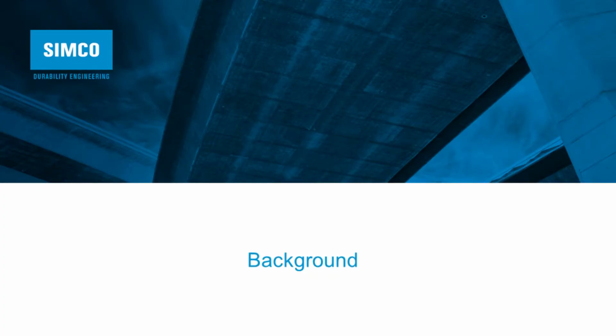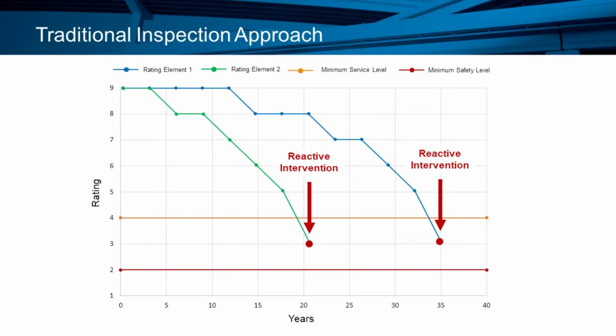Traditionally, inspections are done by rating bridges. This is an example. Ratings can be different across agencies, but the idea is to inspect on a regular basis and then assess a rating on an element or a structure, and as the rating decreases or increases depending on the system, we come to a point where an intervention is required.